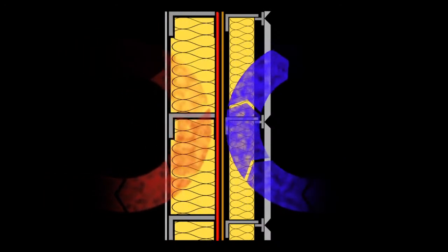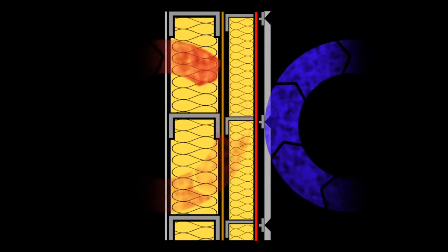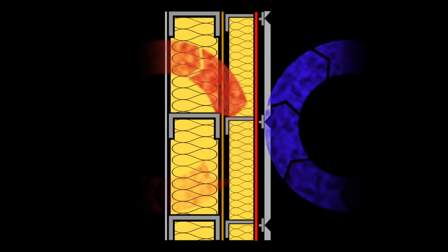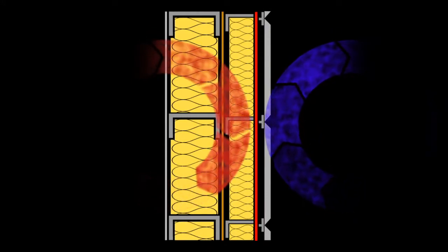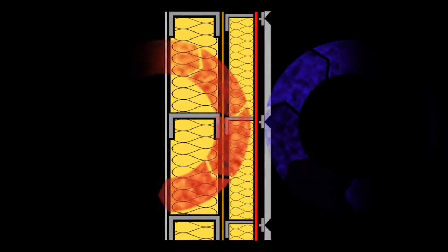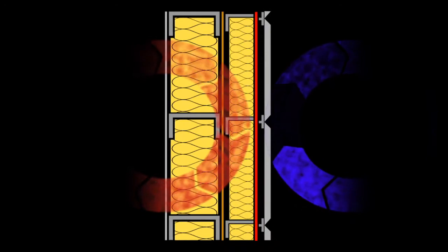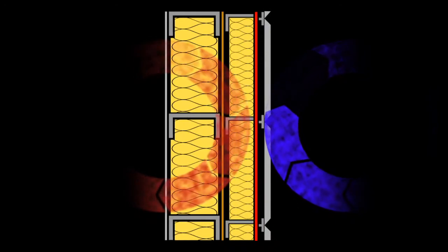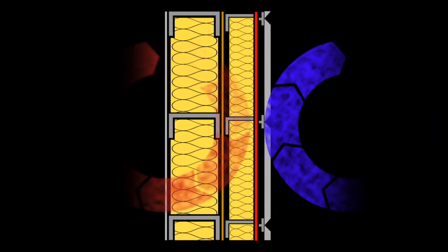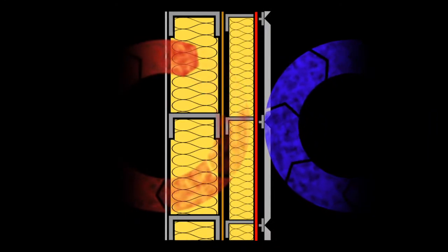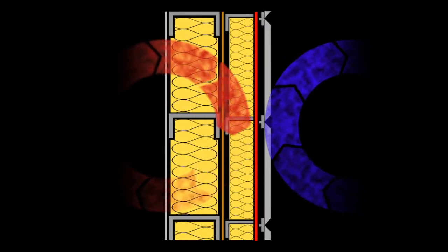By moving the air barrier to the cold side of the insulation, external systems such as our Wraptake allow for an almost penetration-free airtight layer, which can be installed faster and more robustly. Far simpler than internal options, the Wraptake external air barrier system maintains the envelope's integrity with fewer building surfaces and structural penetrations to be sealed and less room for error. Being fully self-adhered to a substrate, it is also better able to resist external forces such as wind loads, ensuring good performance is maintained by minimising wrinkles and poor sealing.